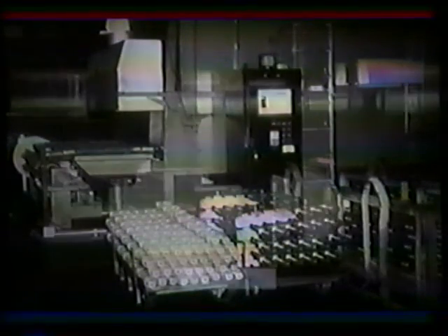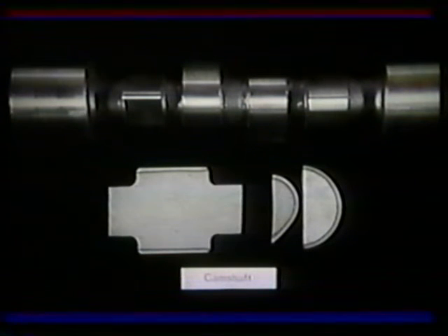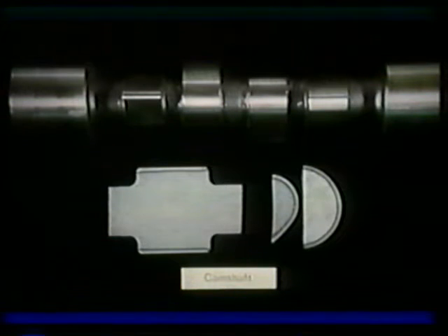The hardness after heat treatment is in the range of RC56 to RC60. This slide shows a cross-section of a journal and lobe and illustrates the hardened case depth after heat treat. This case depth or surface hardening is critical to a long wear life.